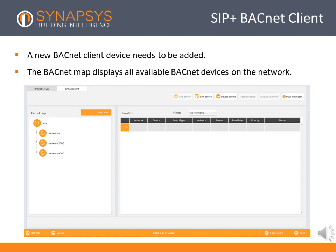Points will be displayed as groups of object types. Valid object types to the SIP+ are analog input, output and value, binary input, output and value, multi-state input, output and value, and accumulators. Refresh the object type header to learn the labels of the points and other information, including the present value. Once the correct points have been found, highlight them and drag and drop them into the table to add them to the list of points to be polled. Points can also be mapped manually using the arrow on the table and entering information in manually.